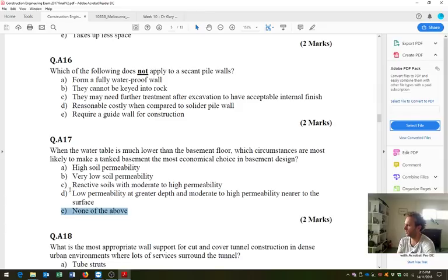I think this is the question you're asking. Okay, we're up to now Bresson's post. How do we increase socket roughness? So we do that by putting a tooth on the outside of the borer. So just a protrusion of steel, and that will sort of cut a spiral into the socket, which will roughen it. Why sometimes we have teeth at the end of drilling rig? So I'm not certain I understand the question, but we have teeth to help cut rock, typically, or just to have more cutting power. But if we've got a sideways tooth, then that helps to add to roughness.